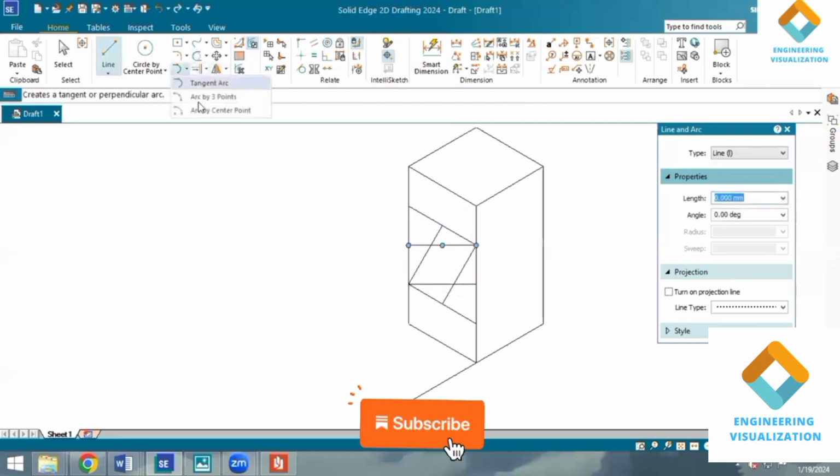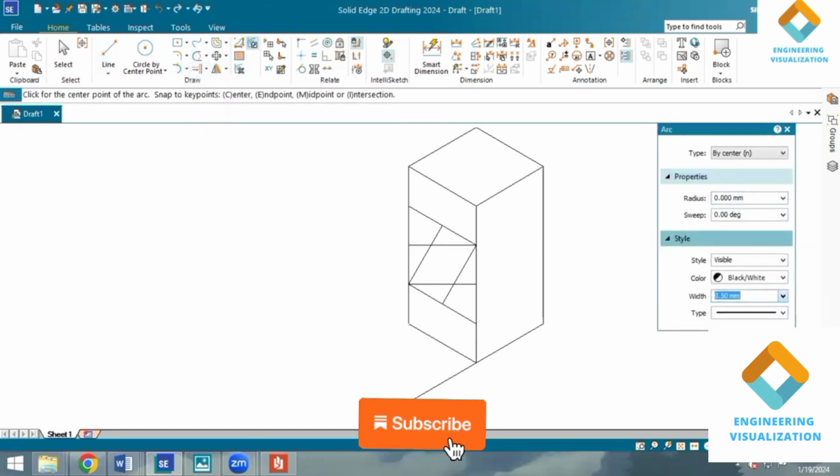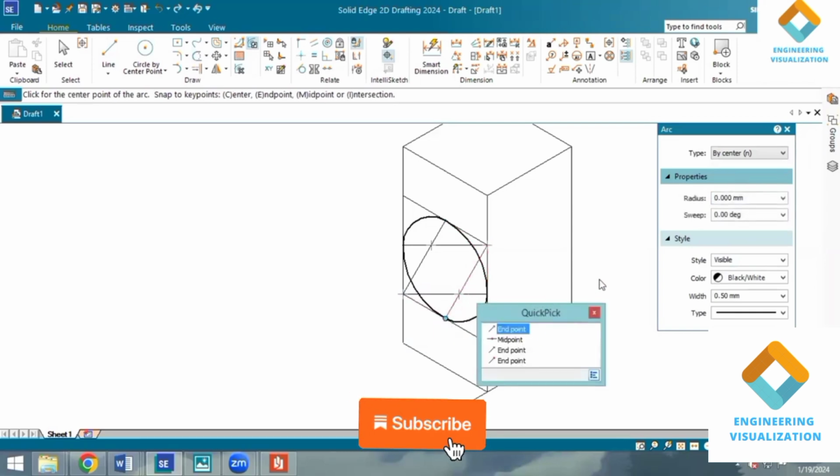So now using the arc by center method, here we will be constructing an arc to construct the ellipse, taking this length, draw an arc. Same way from here to here, take this length, draw an arc. Now for the third point, take this as a reference point, taking this length, draw an arc. And same way here also, take this length and draw an arc. So we have completed an ellipse here.